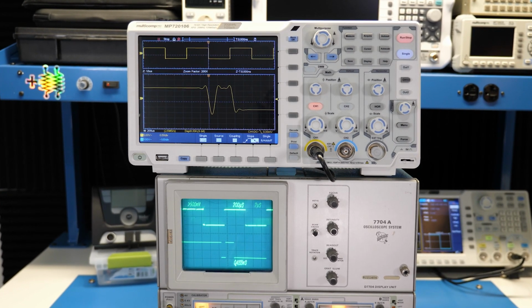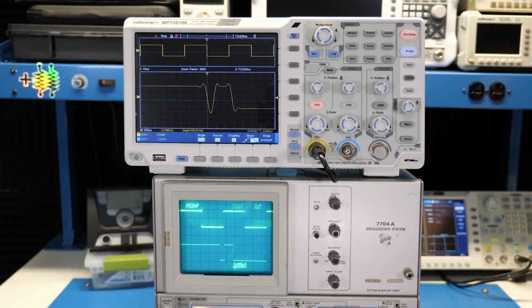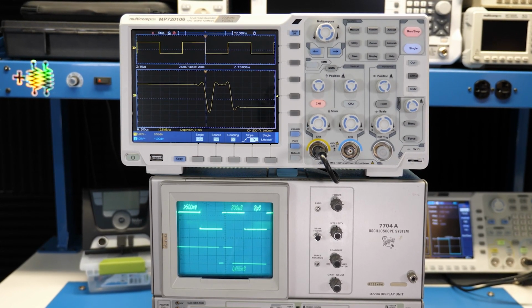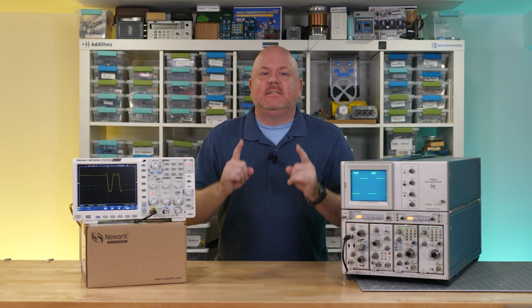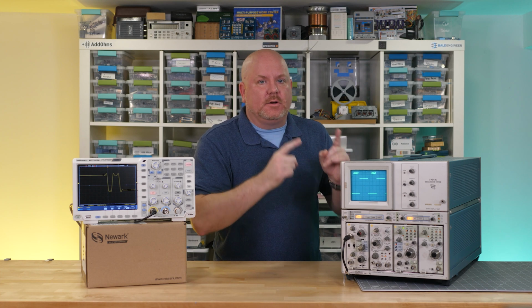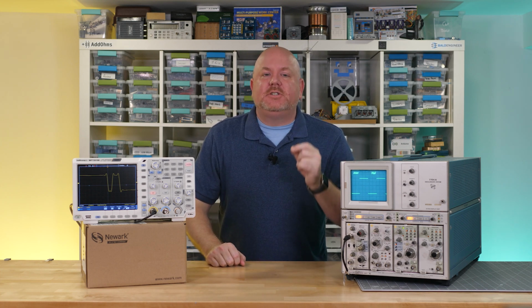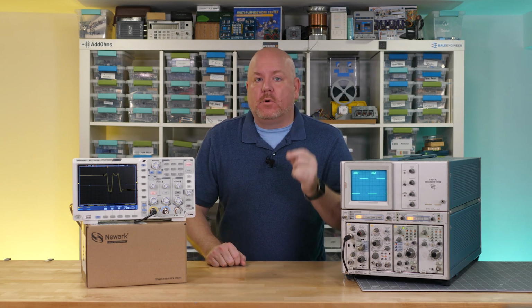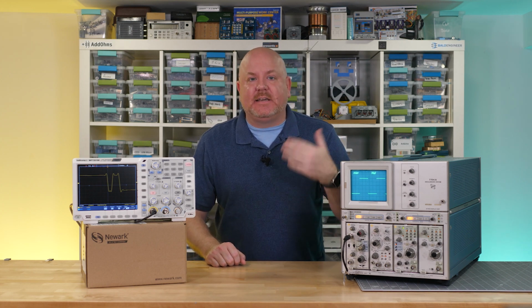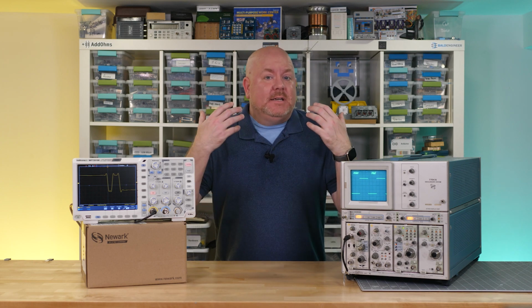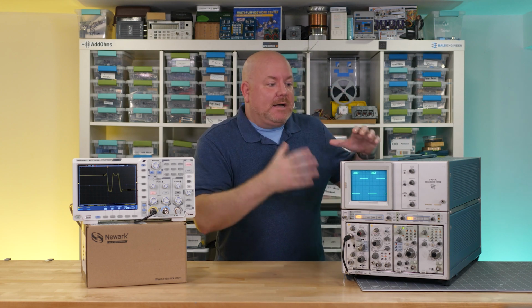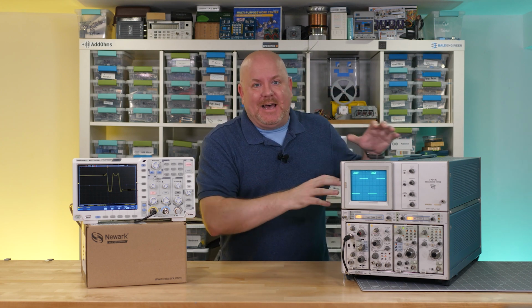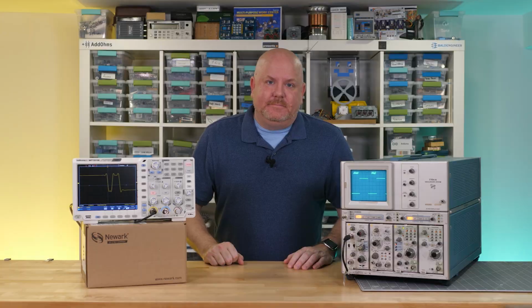And you might even understand now why most digital scopes format the screen the way they do when in their zoom or delayed mode. While this feature is useful and cool, it does have a big drawback being on an analog scope. The waveform and the glitch have to be repetitive in order for us to see them because the CRT has to keep getting redrawn. Now later on, analog scopes did start to use digitizers to try to create a stable display. In fact, there's a module for this system that does just that. Unfortunately, I don't have it yet.